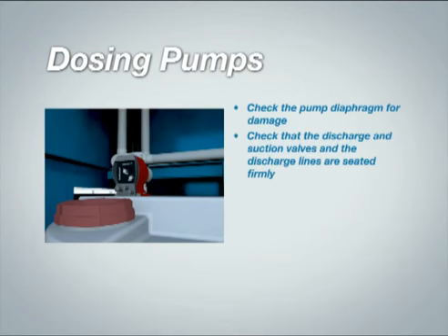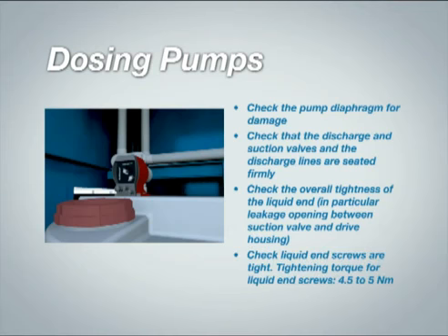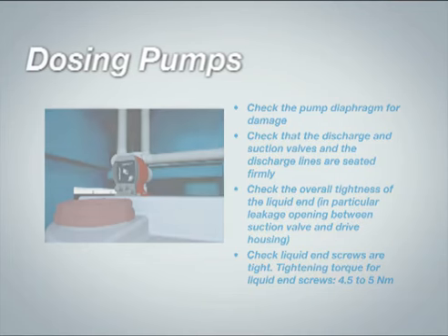Check that the discharge and suction valves and the discharge lines are seated firmly. Check the overall tightness of the liquid end, in particular leakage opening between suction valve and drive housing. Check liquid end screws are tight. Tightening torque for liquid end screws, 4.5 to 5 Nm.